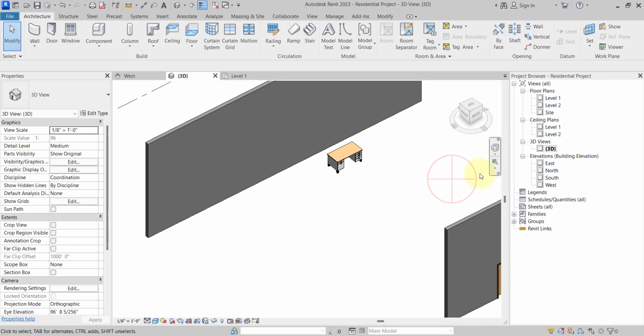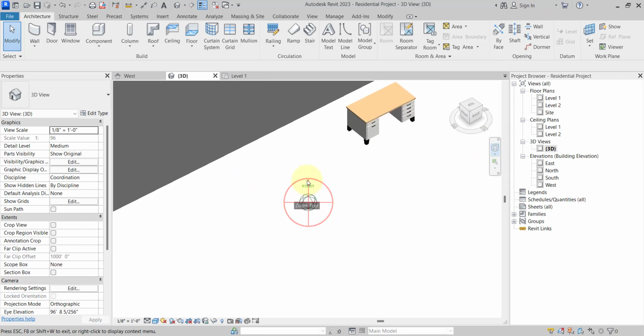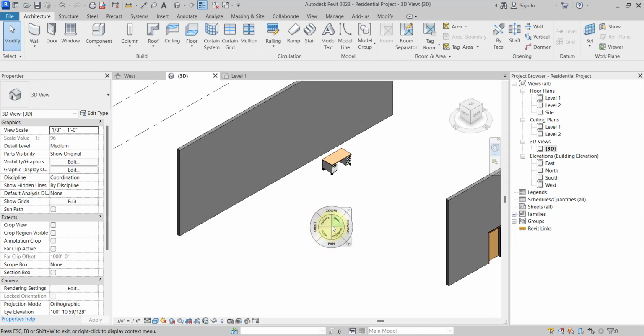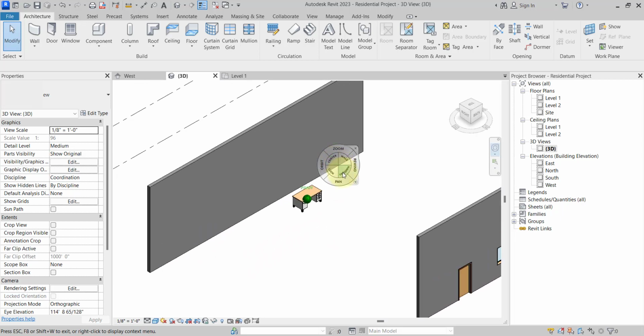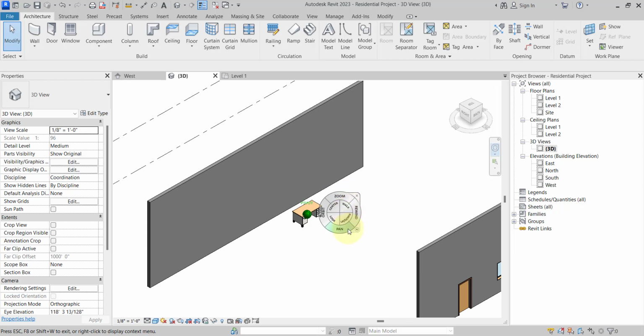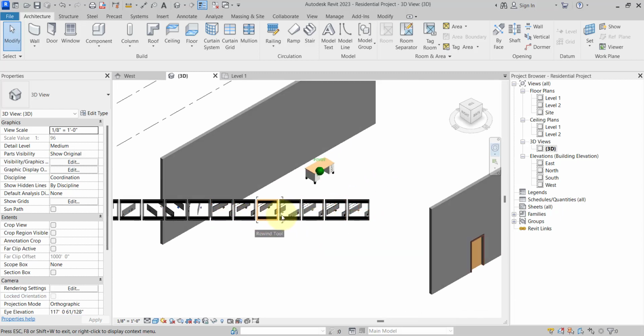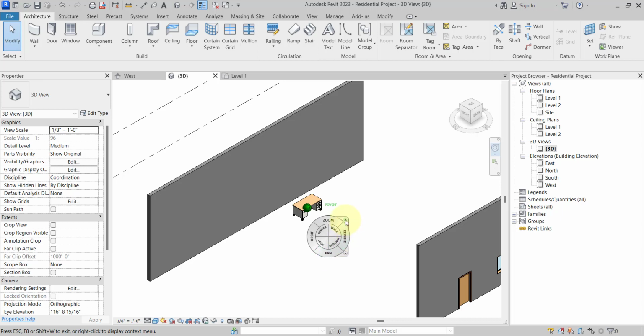So you can easily use this navigation bar for the wheel purpose. Let's say if I click on this icon, I can use options like zoom in, zoom out, orbit. Then after set center, I want to set the center here. Then after I can use up and down. This walk is using perspective, so those things are not available right now. Then after pan, then after rewind, what are the different rewind views there are, and so on, right?